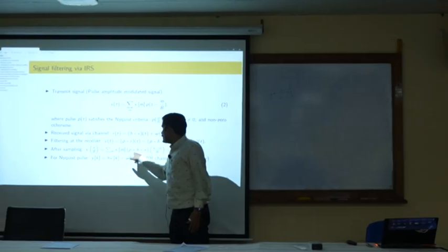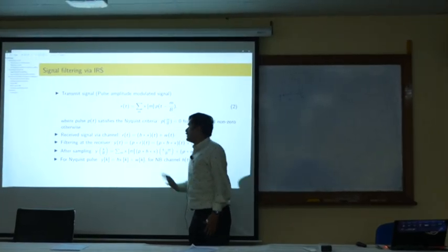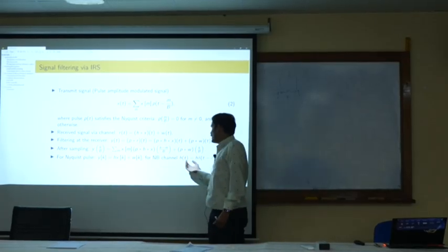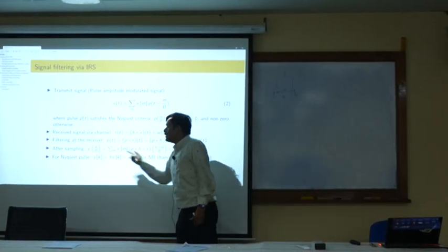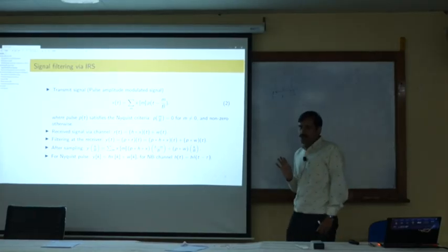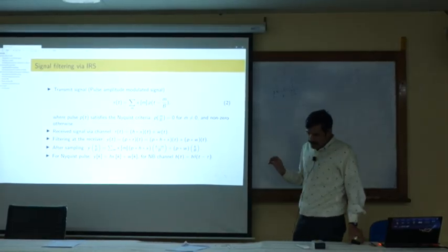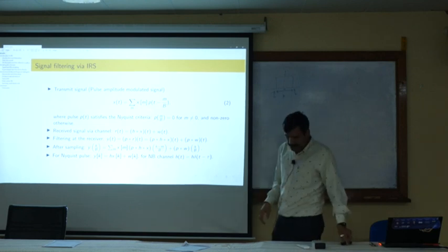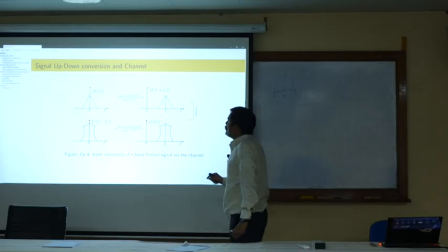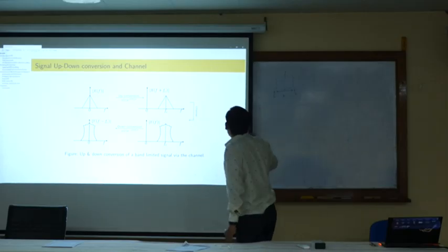We will get some channel here and the corresponding signal, and for a narrowband channel this h(t) will be a simple flat fading channel, only one coefficient will be there. If you have frequency selectivity, there will be multiple taps here. Okay. Next, this shows the similar process.